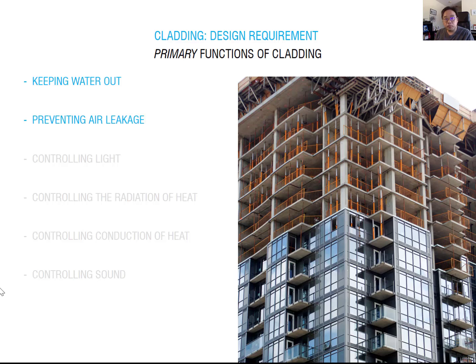I think this is the most important for your facade, for your envelope design. You have to prevent water leakage from rain, snow, ice. Water problems are more of an issue in tall buildings. So you have to have proper detail between the structure and the glazing. How can you design the waterproofing, how can you use sealant, how can you use waterproofing membrane there.